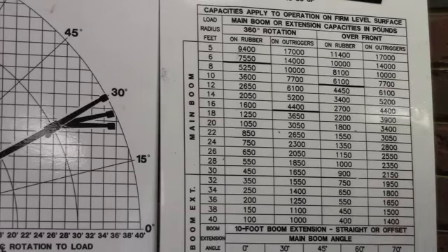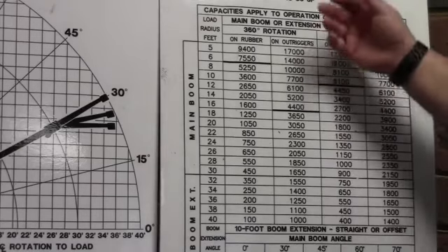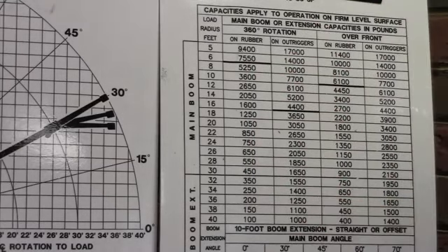So we have to determine which we're going to rate our crane for, 360 degrees rotation or over the front. And it is my preference that whenever you're setting up a lift, unless it is absolutely necessary, you calculate your load radius and your load rating on your 360 degree rotation. That way you don't make a mistake and suddenly rotate the boom and overload the crane.